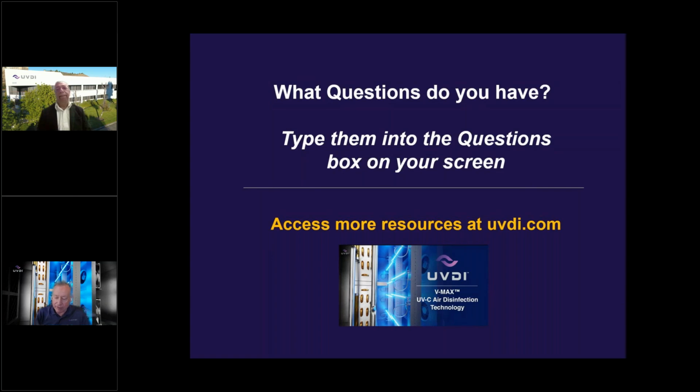Great, thanks. So it looks like there are some questions related to standards. With the discussion of PCO and UV, can you review safety standards for UV? And then is there anything specific for PCO? Yeah, for UVC, primarily it's been 254 nanometer wavelength. There's a standard for photobiological safety, which is IEC 62471, which gets into those details.